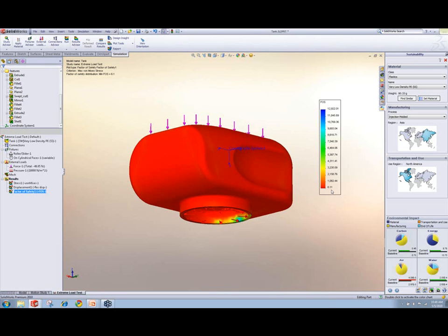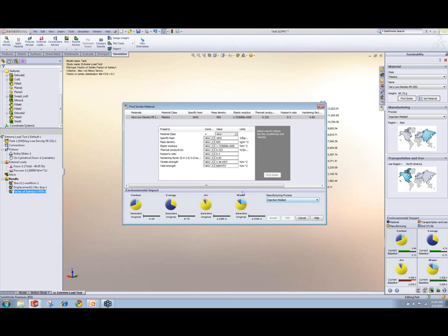We can go in and change the thickness of the tank. Let's keep this going. Let's reset our baseline. I'm pretty happy with this. For now, we're going to use this very low density material. Also, if you want to keep on cycling through all your different materials, you can hit Find Similar, and you can optimize your material, just like we saw earlier.